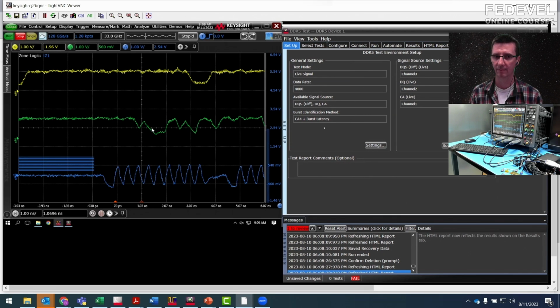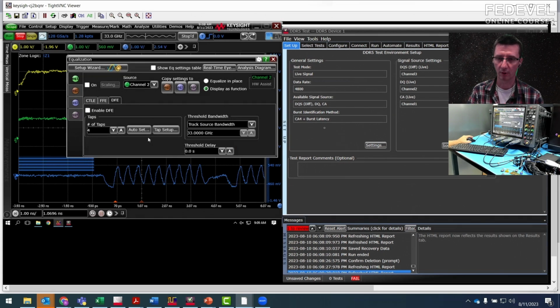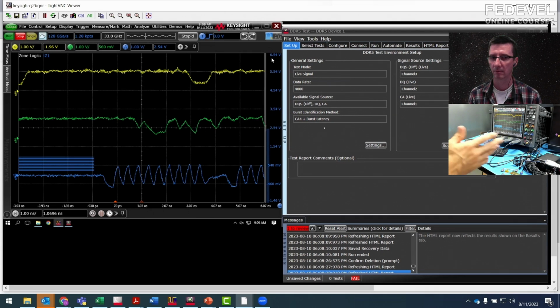They query, they run a report or they query the register values, get those settings, and then you come into this menu and you really see what the memory chip sees. Exactly. Yeah, because now the interposer allowed us to probe as close to the ball of the DRAM package, right?